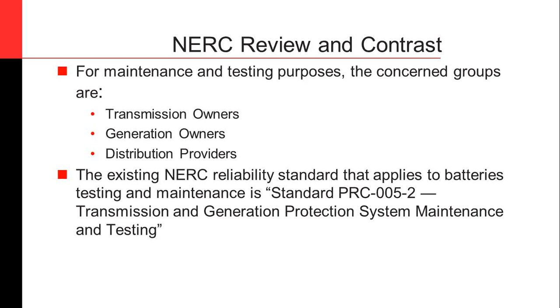And then, okay. There were some correction tables, I think, a few slides ago. Are these from the IEEE 450 standard? Yes, they're contained in both the IEEE 450 as well as the IEEE 1188. 450 is for the vented lead acid or flooded cells, and 1188 is for the valve regulated lead acid.